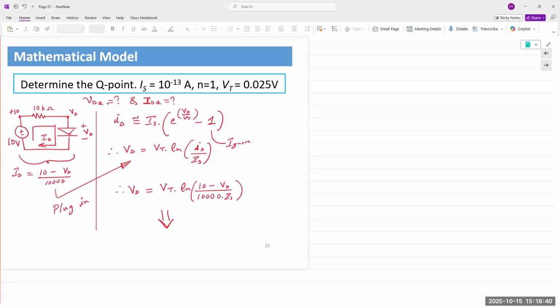So the point of this exercise is that since a direct solution does not exist, we pick a point, right? We are assuming a value. Anytime we make an assumption, what do we do? We go through our analysis or calculation, whatever the case may be, and then we verify the end result. Does the end result match with our assumption? If we choose Vd equal to 0, the answer must be equal to 0. Then 0 is the right answer.